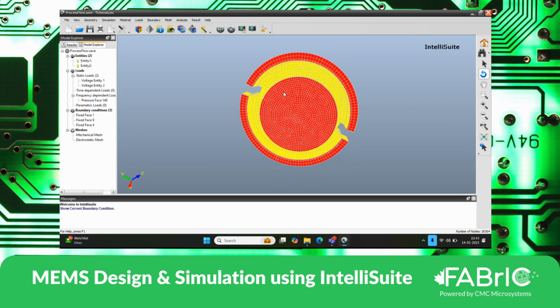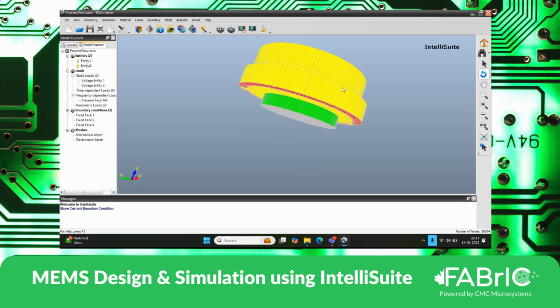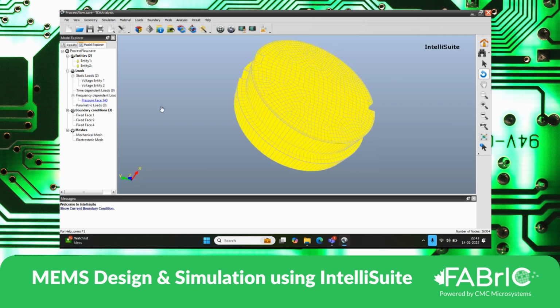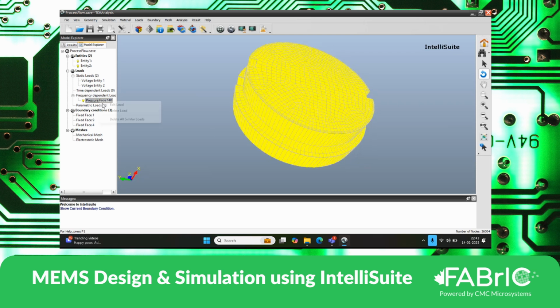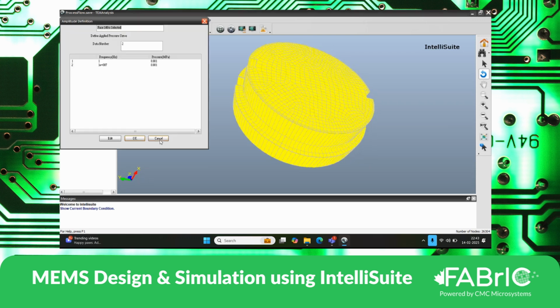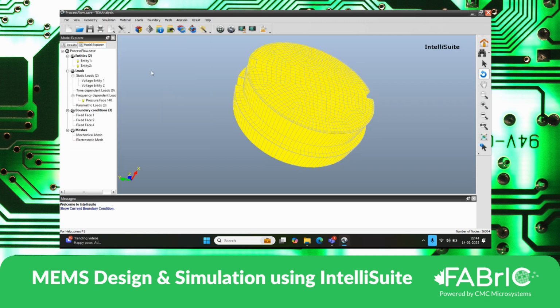Yes, so the boundaries are fixed in these locations and the pressure is applied on the top surface. Oh, probably in this case it's different, I guess. Oh, it's a dynamic simulation. Sorry. Yeah, so here we have applied the pressure on the top surface and we have applied voltage also to measure the capacitance.